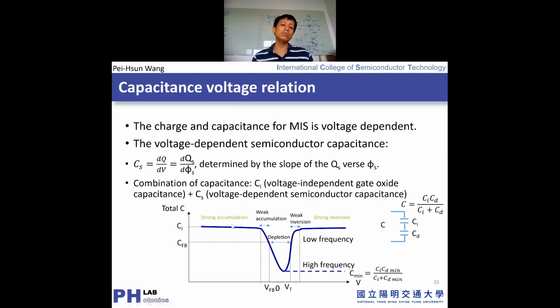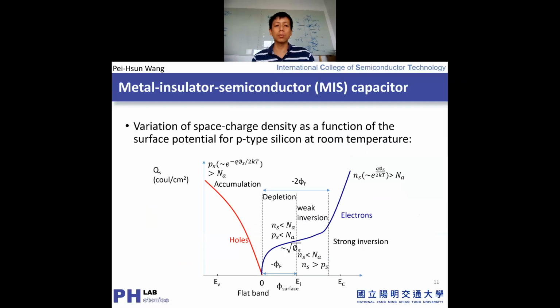If you are working with strong accumulation, typically there is no additional charge distribution because with accumulation, there's only hole accumulation. That means you get a positive charge along the semiconductor and a negative charge along the metal. So it just works at the same time.